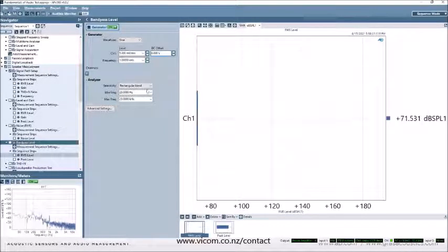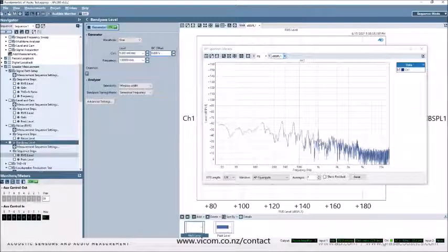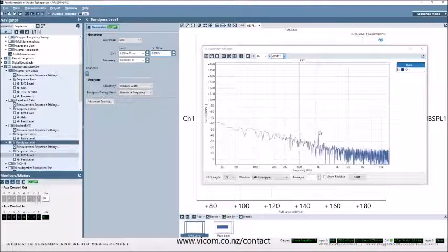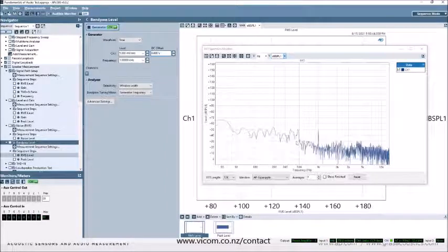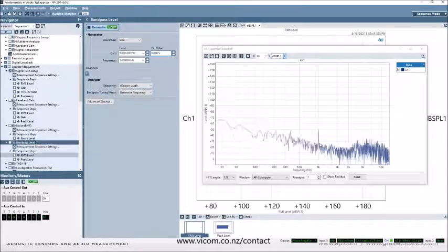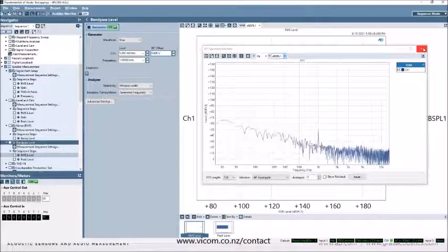Now what I could do here is say, actually, I want to measure the noise within the narrowest band possible, which is called window width, at 1 kilohertz. And now I can actually measure the output level of just that speaker because our measurement is only making a measurement of level just at 1 kilohertz. It's ignoring all the sounds that are adjacent.